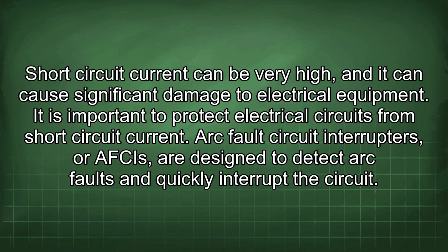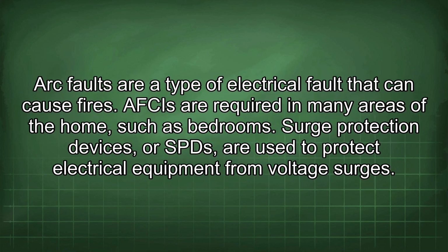Arc fault circuit interrupters, or AFCIs, are designed to detect arc faults and quickly interrupt the circuit. Arc faults are a type of electrical fault that can cause fires. AFCIs are required in many areas of the home, such as bedrooms.